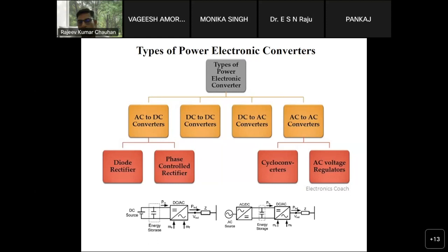and DC to AC. In the figure below, I have shown how we are going to integrate the DC based source as well as the variable AC power source. A DC based source can be integrated by using a single DC to AC converter, and we can also include the energy storage. When we have a variable AC source, we use a back-to-back AC-DC as well as DC-AC converter, and in between, at the DC link, we can also integrate the energy storage.